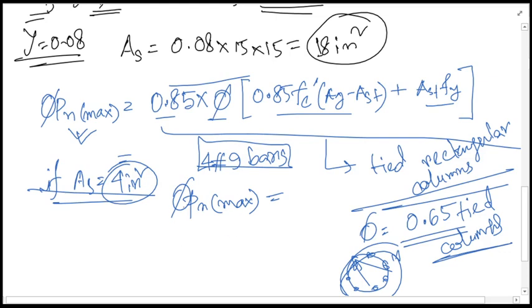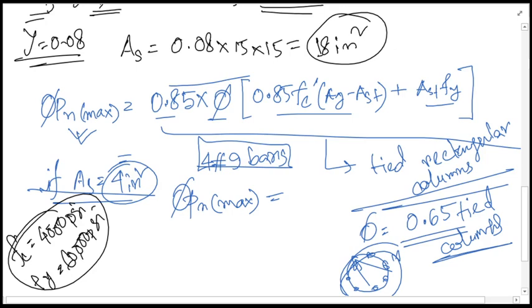So whatever it is, for the phi Pn, if we use, for example, in this particular case, the strength will be changing. The f'c value will be 4000 psi that we'll be using, and fy we will be using 60,000 psi. Although in beams we have used different values, for columns we will be using these values, which will make our calculation simplified, but not necessary for your case. For your case, the strength might have been given to you, and that particular strength you will be using. However,